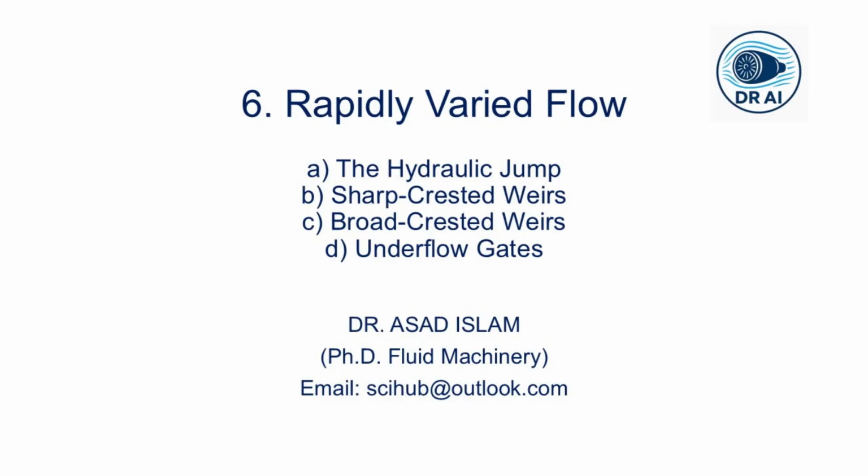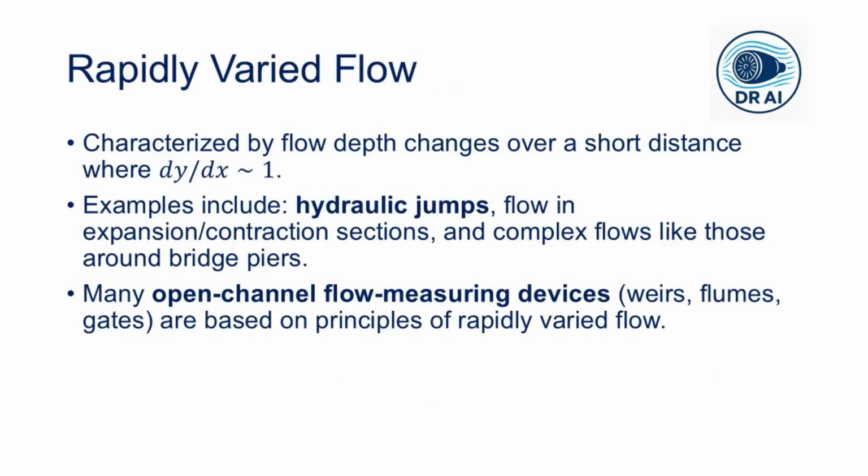But let's be very honest, as exciting as the gradually varied flow is, it's, well, gradual. But today we are going to look at the other end of the spectrum. We are going to look at the rapidly varied flow, or RVF. This is where the depth changes dramatically over a very short distance, where the term dy over dx is on the order of 1 or even approaches infinity.